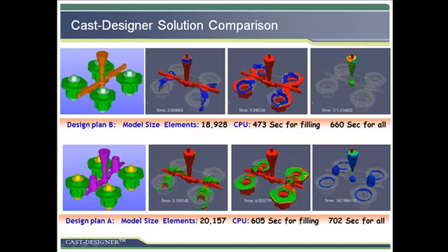This is an example to compare 2 design solutions of the casting system, the second one with 2 risers, and the first one without. However, the inner gate of the second case was not designed well, so the riser cannot compensate for the shrinkage problem. So the first design, with a higher yield ratio, is still better than the second one for shrinkage porosity. Both simulation times are less than half an hour.